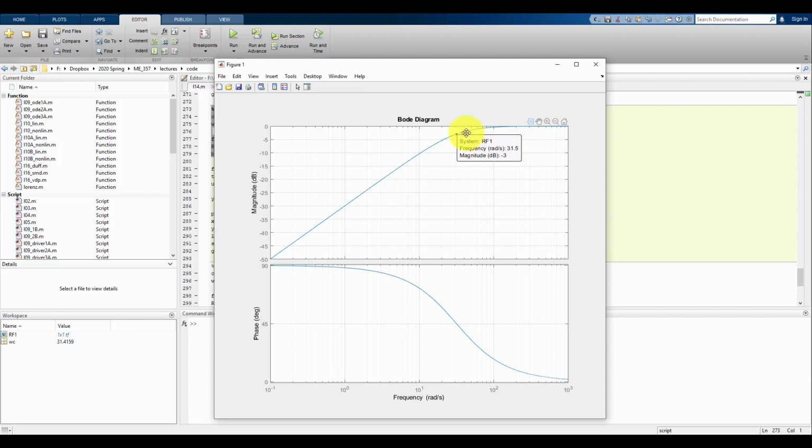So now we can check how each part of our signal is going to be affected. So we want to find that 0.5 radians per second and the 100 radians per second. All right, so the low frequency is going to have that attenuation, -36 decibels. And we're going to see that the high frequency now, the 100 radians per second, is going to have a magnitude of -0.4 decibels, so fairly close to 0.